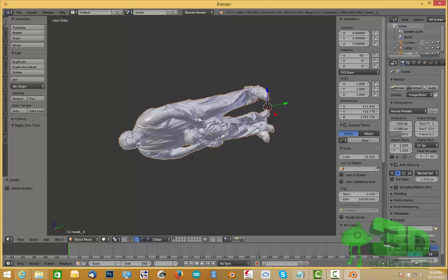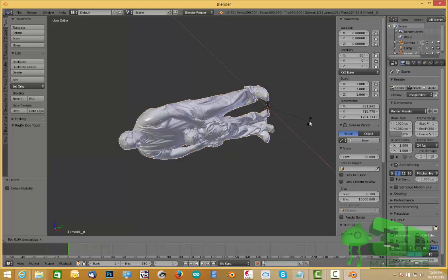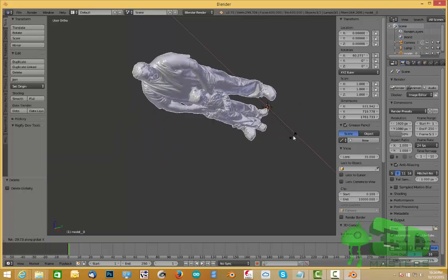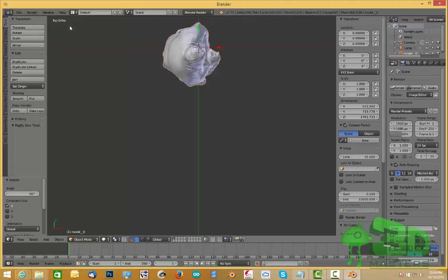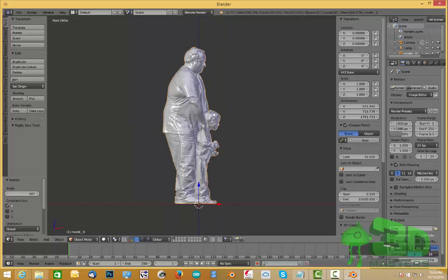So what I'm going to do is rotate this into position. I'm going to hit R and then rotate on the X, and you notice that line came up. So R and then X, you see the line that came up right here in between. What I want to do is hit -90 and then hit Enter. Then, since I'm still in orthographic view, I want to go overhead view. If I hit 1 on the num keypad, you notice that I'm not in the front of the picture here. And what I want to do is put us facing the front.